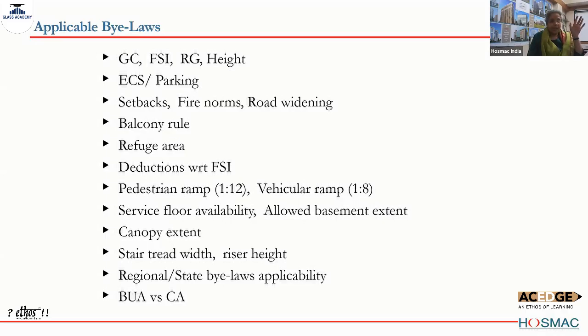So something like 4.9 meters will not do. It has to be multiples of 300, 150 mm. So 3.75 is the correct height. Will give me 3.9, it gives a 3.9. Then it goes to 4.2, okay. So hospitals need to have higher heights than residential buildings. Residential buildings are usually built in 3 meters, which is 10 feet.